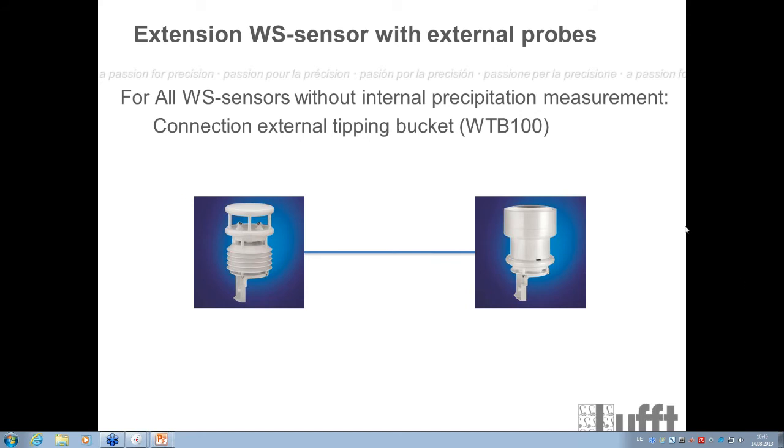The troubleshoot is very easy, because if the client changes the ID, the baud rate, or also the protocol, I do not know if you know that we have a security mode now. After a power reset of the WS, that means if you power off and on the WS, for the first 5 seconds all the WS will start up with the standard configuration.